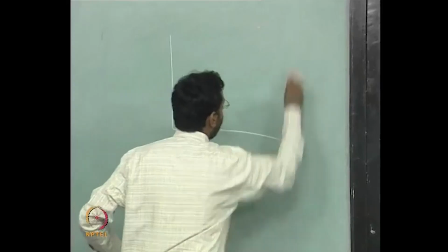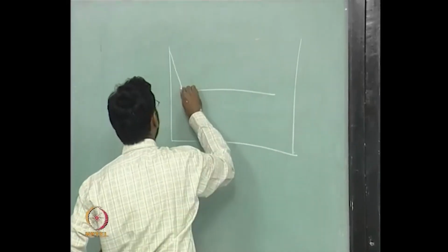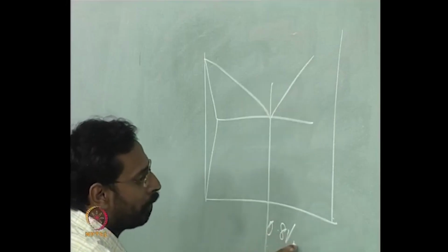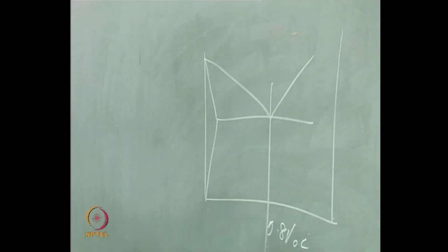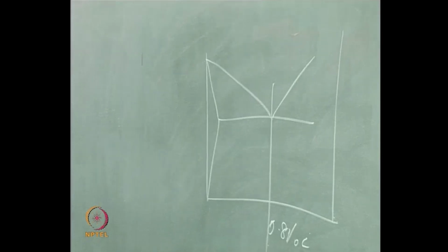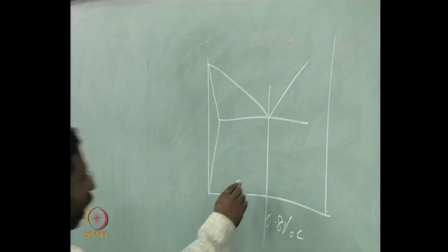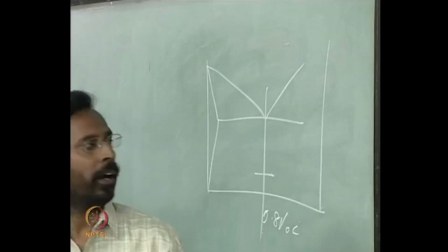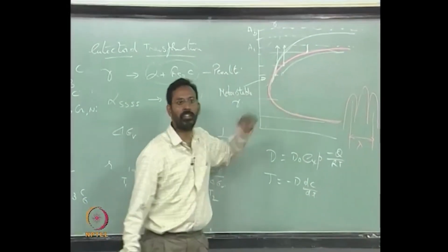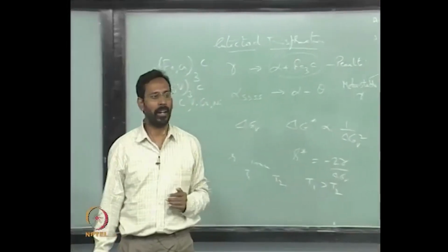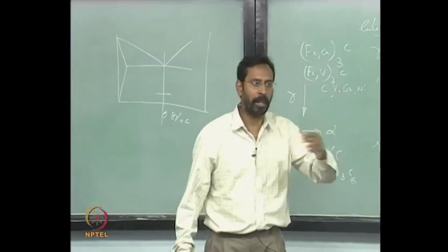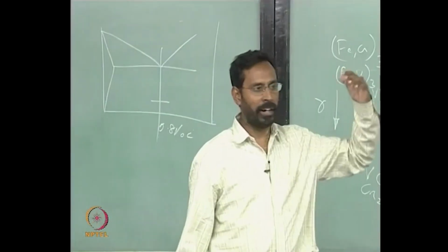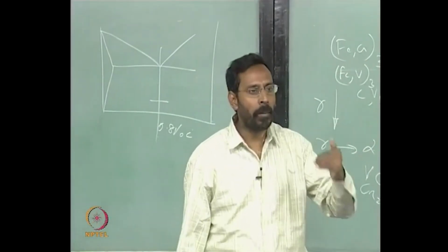So if I take the alloy, we are talking about this alloy 0.8 carbon plus some alloying elements, all of them are in a dissolved state, and the whole alloy is quenched to a low temperature, something below the nose, into the second half of the C curve. Once I come there, because the diffusion of carbon also takes time, because the temperature is low enough, iron itself is difficult. Okay. So carbon also takes time.